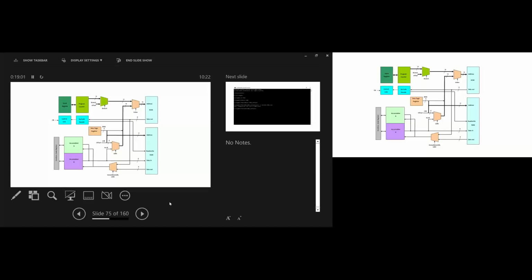And the code automatically generated what's called a MIF file, the Altera memory initialization file. So if you change your code, it automatically generates the MIF file. You just compile the FPGA and it will automatically integrate your code. Because the processor is small, everything is using internal memory. Of course, that's not going to work now with Efinix because they don't recognize MIF files.